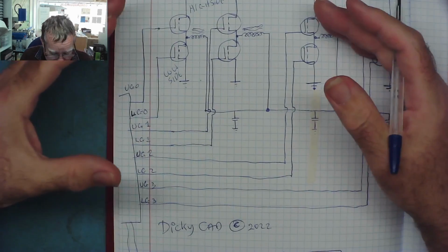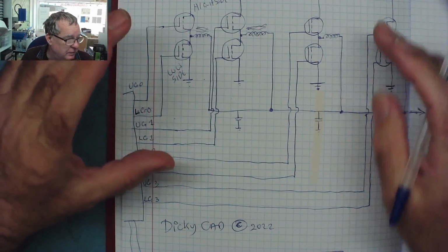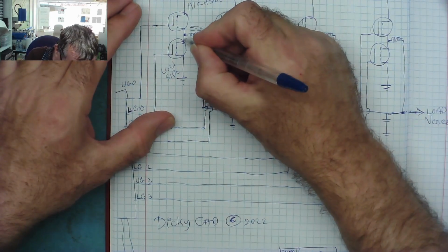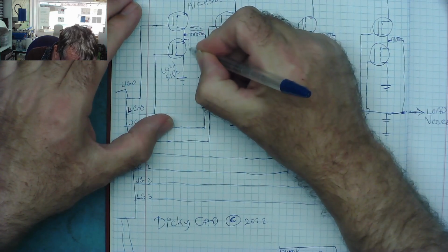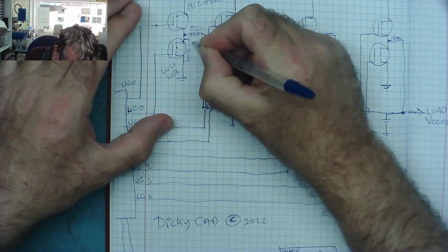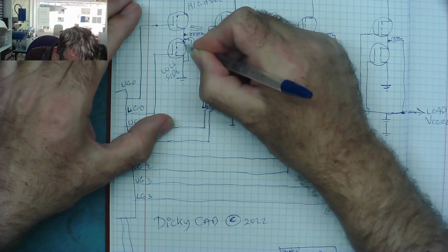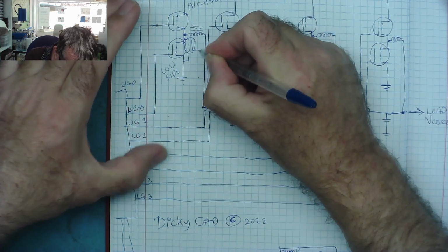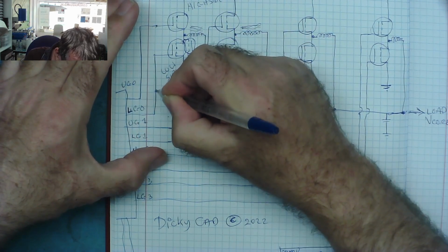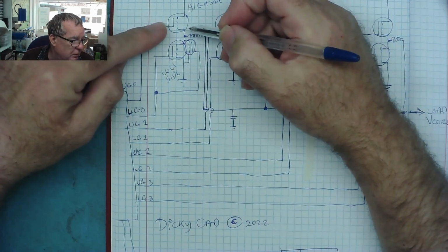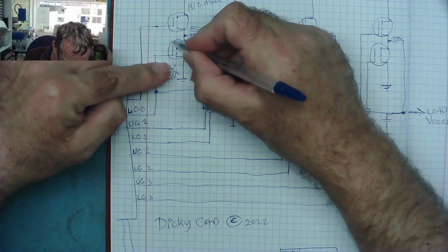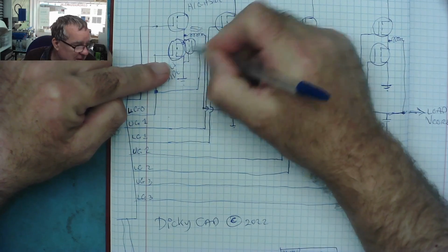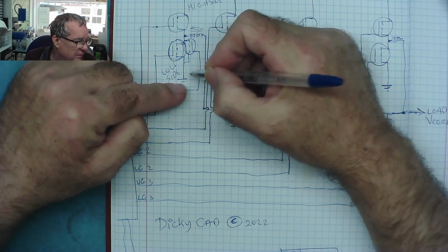Just to add on to this, normally there's another MOSFET here for each of the low side. So normally each low side has 2 MOSFETs, and the gate of this one is connected to the gate of this one. So this switch is on alone to charge the magnetic field, and these 2 in parallel switch on together to discharge it.